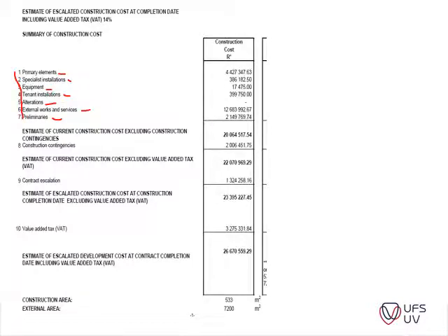Obviously you then calculate your construction contingency on top of that. You add your VAT to that, and then you get your estimate, which is much more accurate, and from that you have your areas that you can calculate your rates with. You will see there's a little section that I cut off here because this is part of the component level that will be included when you get into the more accurate methods.